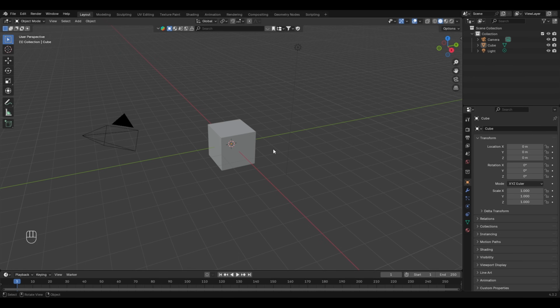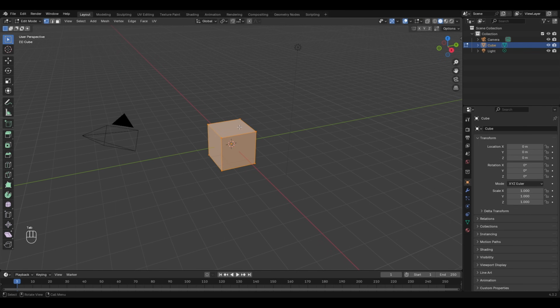Today we are going to make a volleyball. This is our default mesh. We need to add some subdivisions. Go to the edit mode and add some subdivisions. Go to this tab and set the number of cuts to 5. Now we have our cuts.